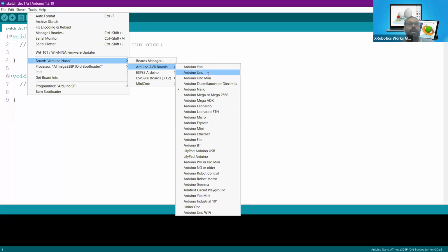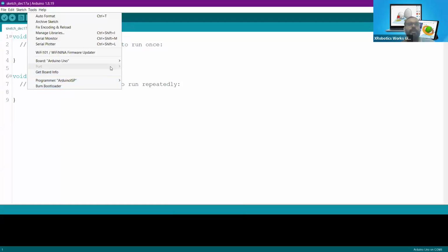So you have to choose the Arduino, and further you have to select a proper port for your board. Right now, no port is visible in this computer because the hardware device is not connected with the system itself. So what I will do is plug in the microcontroller to my computer. Let's see what changes after connecting the microcontroller.